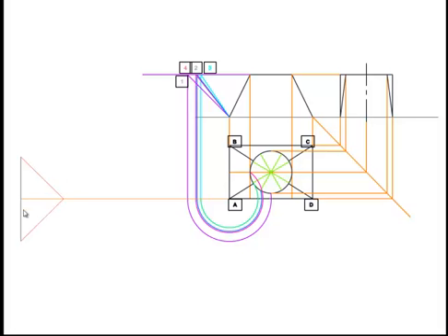Now we can take the 120mm line and divide it, which is 60 here and 60 here, as in plan. In the elevation our overall distance between A and D is 120. This point here is located by stepping off our radius, which is located from the purple line from both ends.